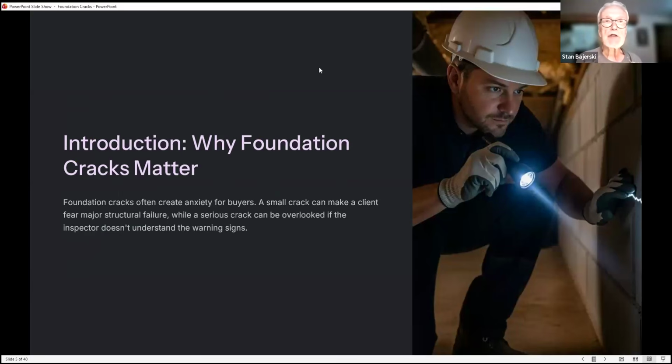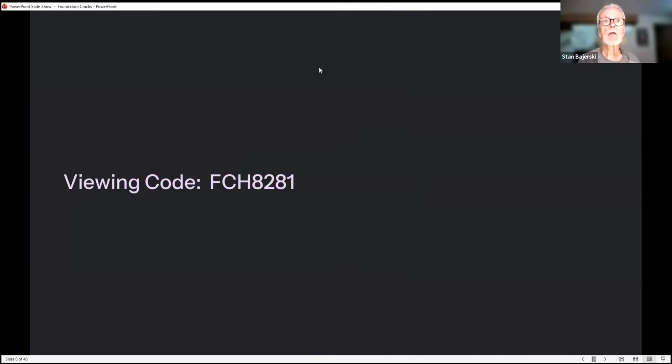So why do foundation cracks matter? Well, first of all, when people see cracks, most of them are a little bit taken aback, right? So you're probably going to have to look at it yourself and figure out where you think you stand on a matter and then convey that information to your clients. Foundation cracks often create anxiety for buyers. A small crack can make a client fear major structural failure, while a serious crack can be overlooked if the inspector doesn't understand the warning sign. So it's really up to us to put things into perspective.